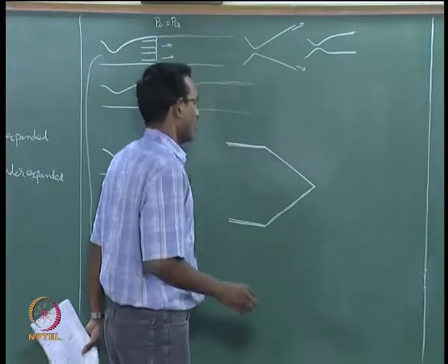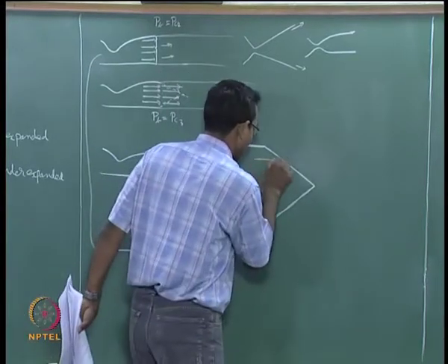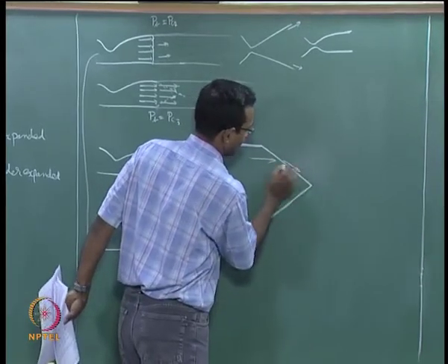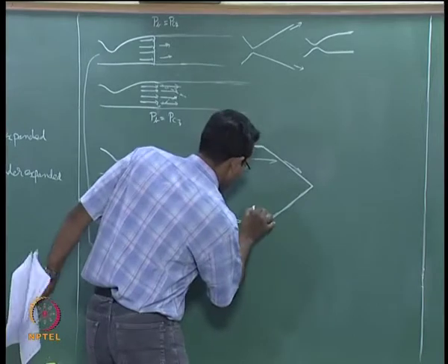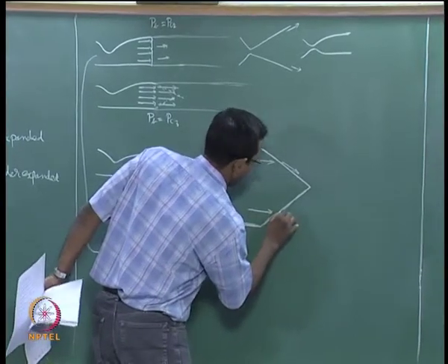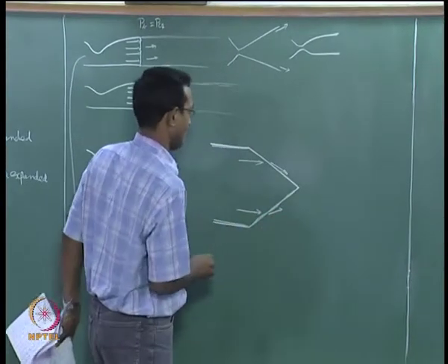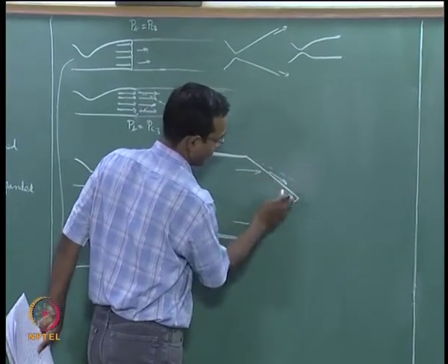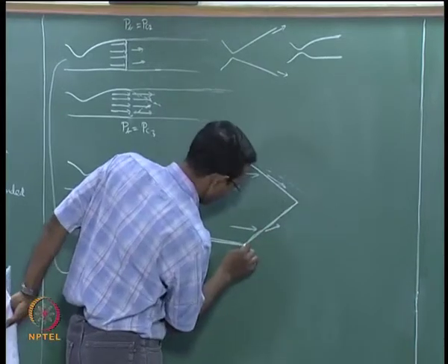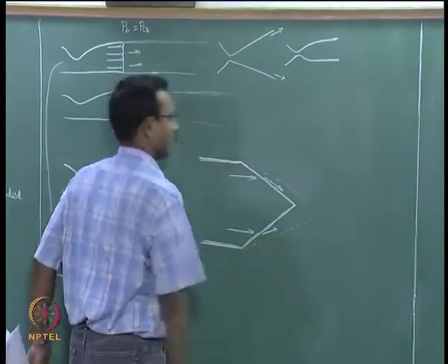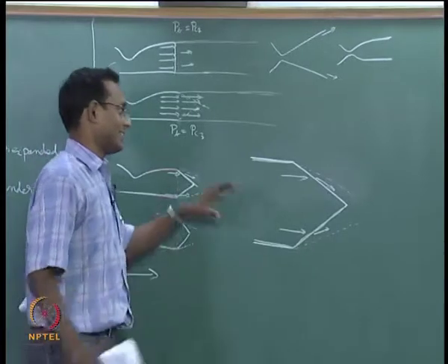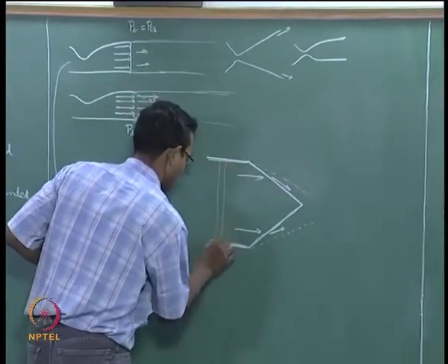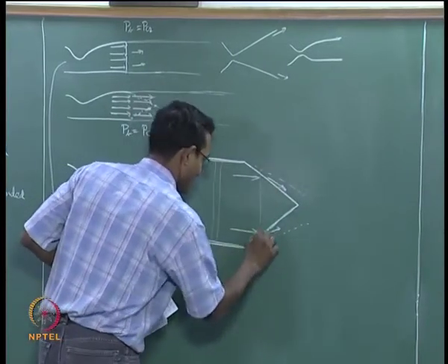Okay. Now the fluid element here is coming at this angle and because of the oblique shock it is turning like this. Same thing here and it is turning like this. And so my jet boundary is going to be parallel to these post-shock vectors, something like this. And you can say that the jet, that full slab of fluid which I think about somewhere here, has now shrunk to this size here.